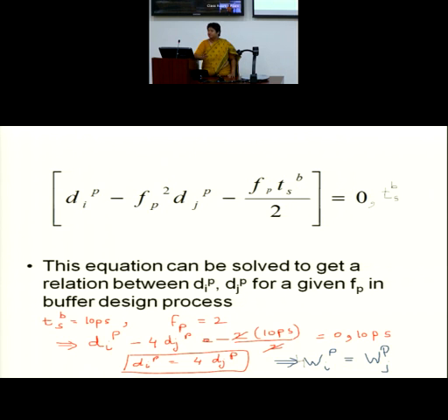Today's CDNs are very, very complex, where very complex mathematical algorithms are used, like the simplex method or Newton-Raphson method, to do the designing, but everything is ultimately to keep the skew within bound. Ultimately everything comes down to the designing of the transistors or the designing of the wires. But that comes with the guidance coming from the skew permissible limit.